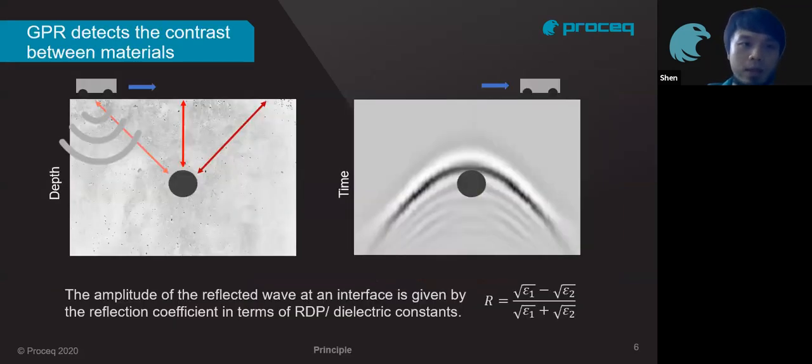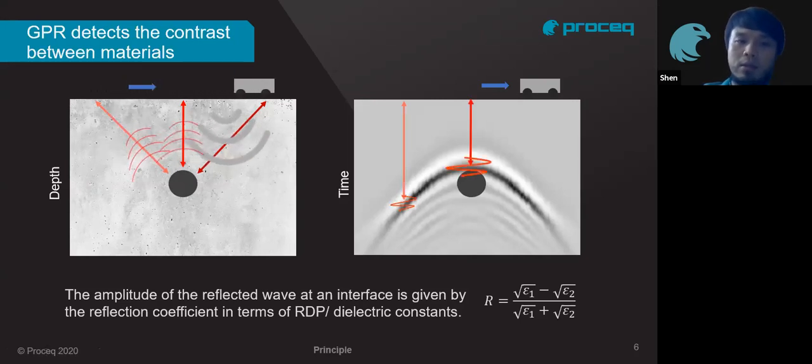So a very quick discussion, or maybe to share with you how GPR actually works in capturing a signal. In this image, this is a concrete structure, and embedded inside the concrete structure is a metal rebar. The little device above is what we call a GPR. As we move along the surface, it captures the reflected signal at every location where it moves.